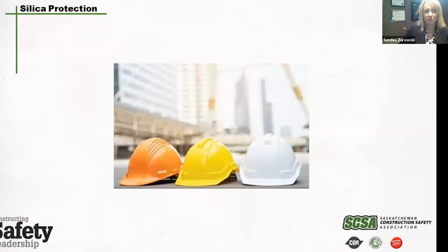The hands and face should be washed outside of the dusty area before you eat or smoke. Educate workers to understand the hazards associated with crystalline silica. Workers must participate in training and monitoring programs. Occupational Health and Safety Regulation 350 states cleanup of work sites.